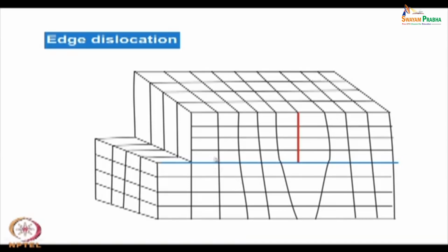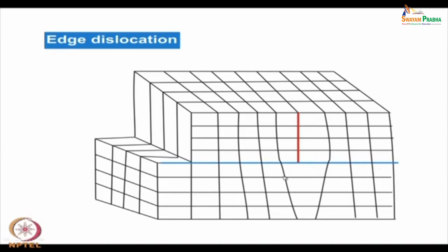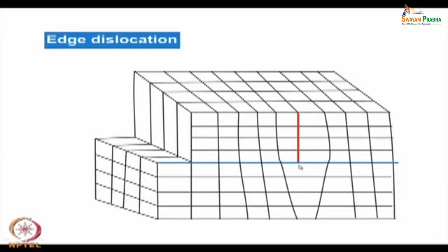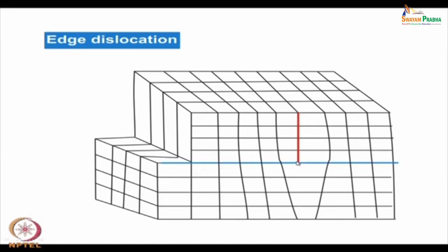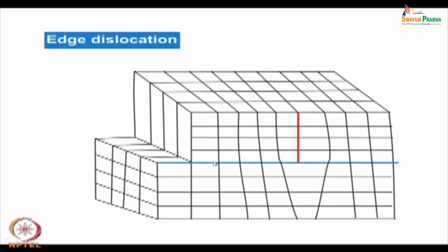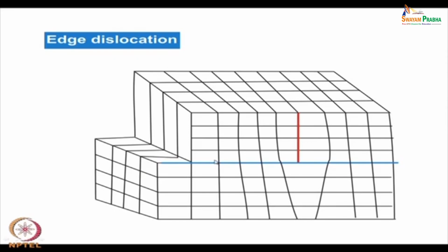If you go on pressing this, another thing we must discuss: at the very first step, this dislocation, the extra edge, would have been one step away, and as step by step movement takes place, that extra edge shifts from the left to the right, slowly, and more deformation takes place.